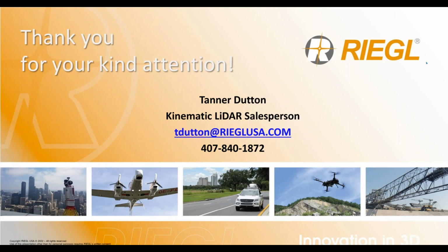So if you wanted to make an adjustment to the terrestrial scanner, you could, and also vice versa. If you wanted to hold the mobile data to the terrestrial scan, you could do that as well in those areas. So yes, you can run RI precision once the data's in there. And you can also use the scan data adjustment to manually do that if you wanted to instead.